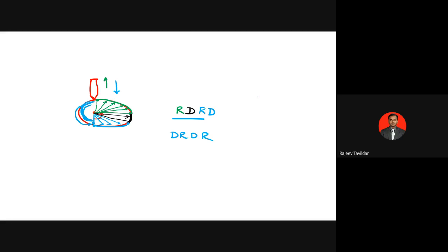On the other end, if I draw a cam profile, something like this. So you can see that starting from this point, okay, the radius is continuously increasing up till here. So this falls with rise too. Again, starting from this point, you can see that the radius is continuously decreasing. So it is a return. Again, you can see that there is a radius with continuous increase. So again, it is rise. Then further again return. So this type of cam, wherein you don't find any profile with the constant radius, this is called as rise, return, rise, triple R type of cam.